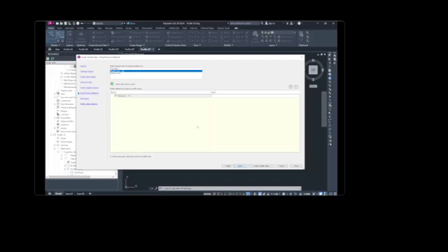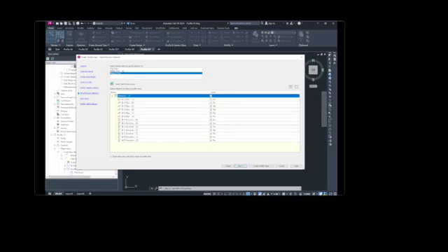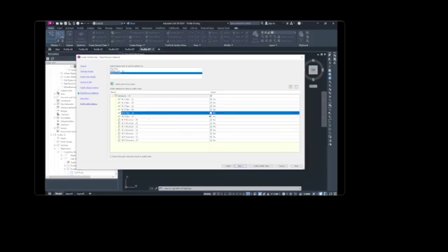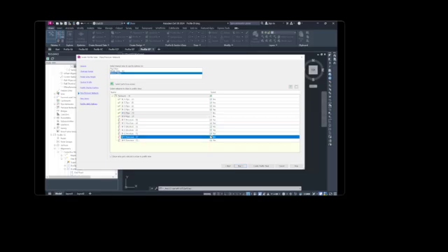Pipe network display. In the stacked view to specify options for list, select bottom view. Select the checkbox, expand the network, clear the checkboxes for WE pipe 1, WE pipe 2, WE structure 1, WE structure 2. Good.